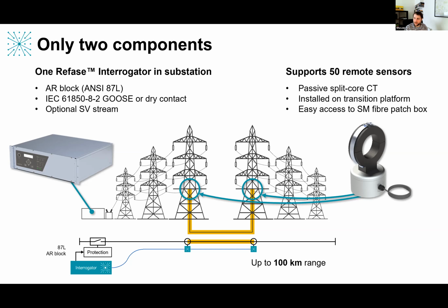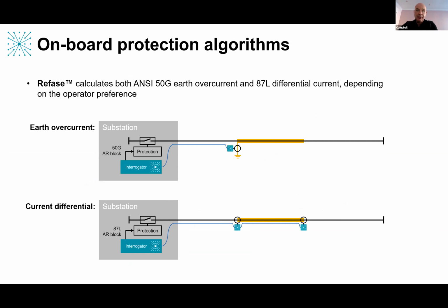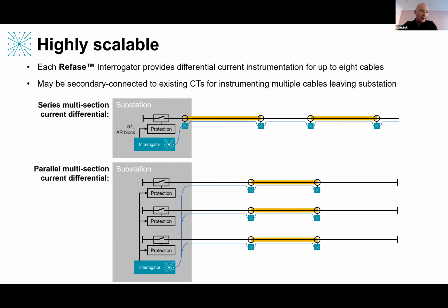Yeah. So effectively a multi-zone differential, where if you had 3 overhead and 3 underground sections, that would be 6 individual differential measured areas, and you would look at the currents going in and out of each of those sections to identify when there's a difference. You know exactly in terms of the section where that fault would be.